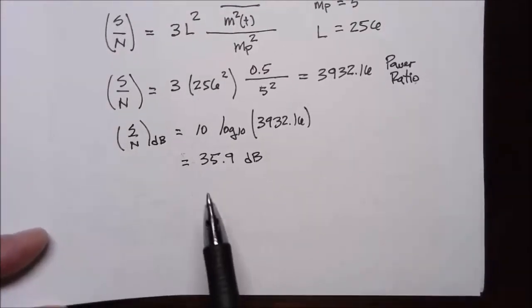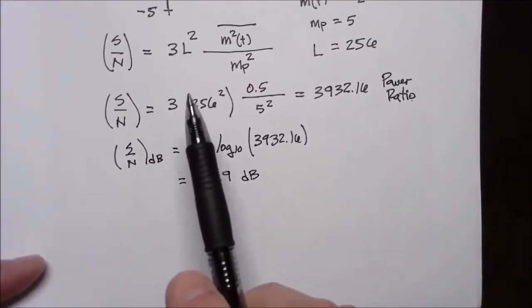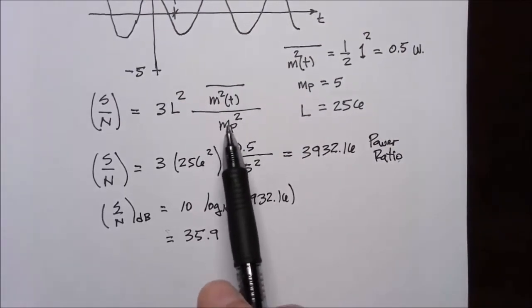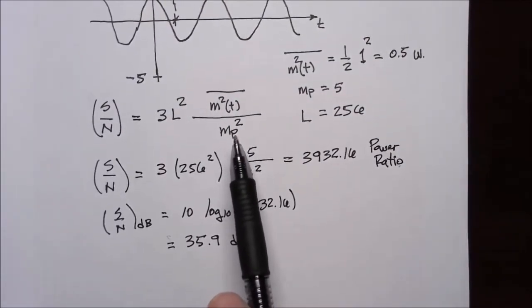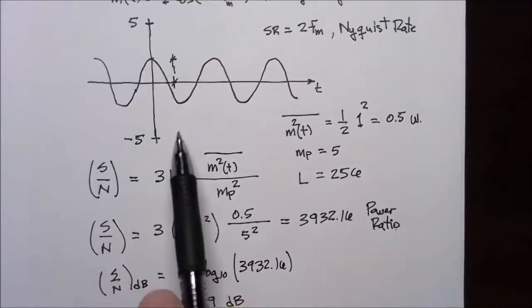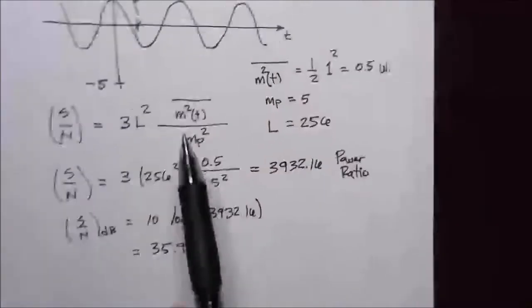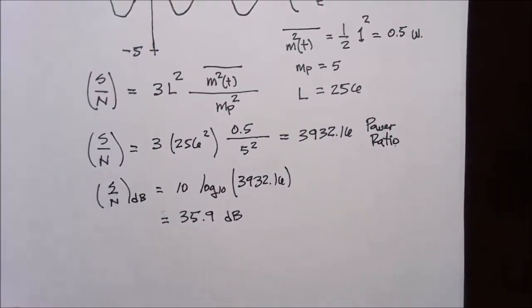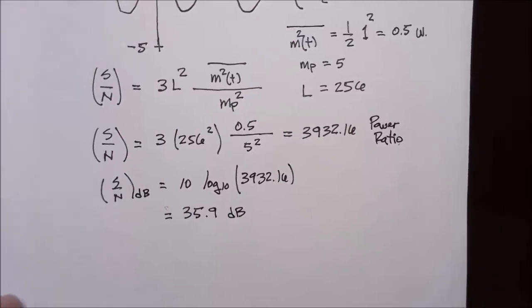That would increase the signal to noise ratio. Or we could fit the peak range of the digitizer more closely to the signal. If we had a smaller peak range on the digitizer and the same number of levels, that would also increase the signal to noise ratio.